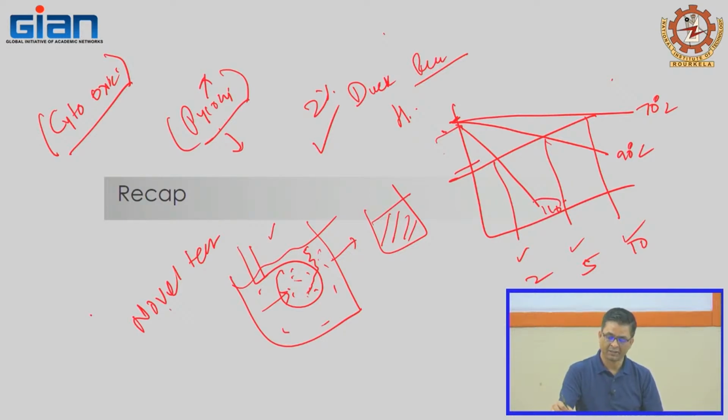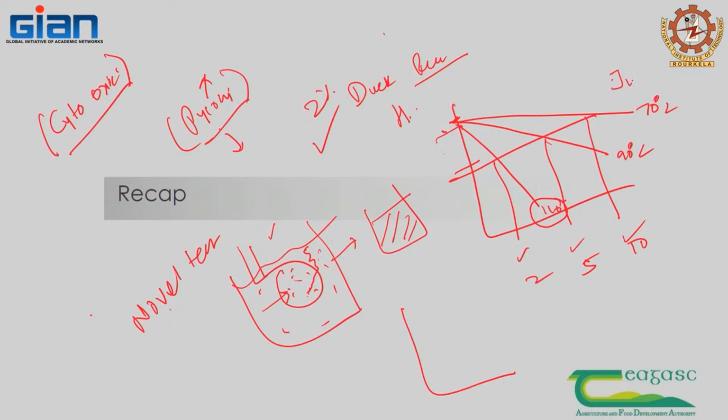But now it becomes a complicated one. Take a product, say juice, and do the ascorbic acid kinetics. In 2 minutes at 110 degrees, ascorbic acid follows this curve, 70 degrees is like this, and 90 degrees like this. That means 90% of ascorbic acid is gone in 2 minutes, whereas when doing it for 10 minutes, only 15% is gone. So selection of the condition depends upon what the other things are.